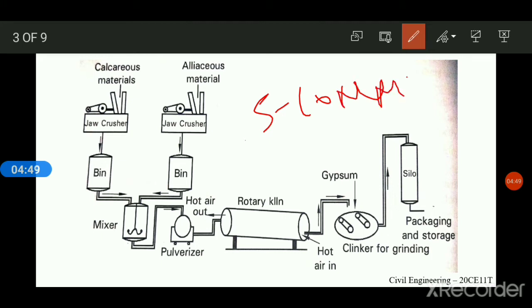As clinkers are coming from the burning zone, they will be very hot, and finally the clinkers are cooled down by air admitted counter-current at the base of the rotary kiln.